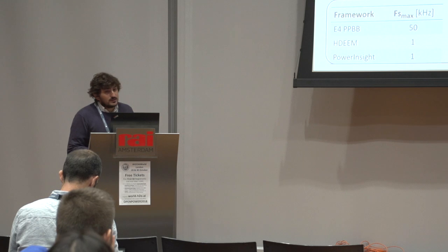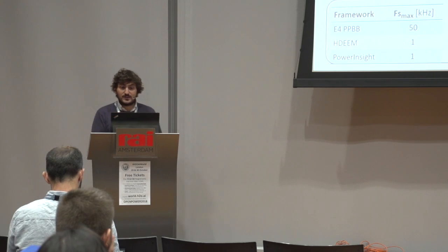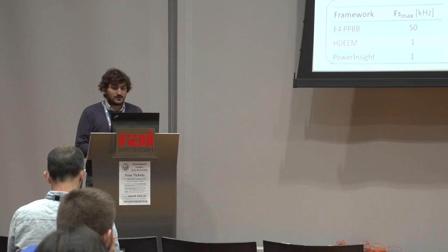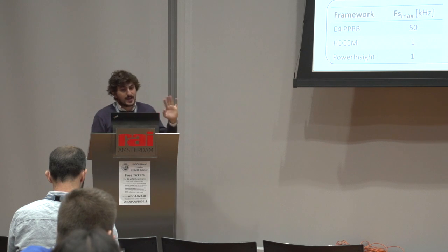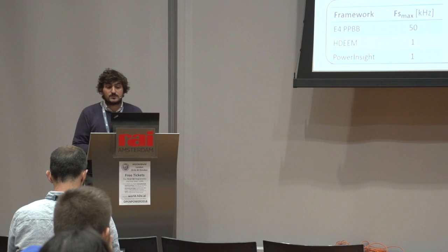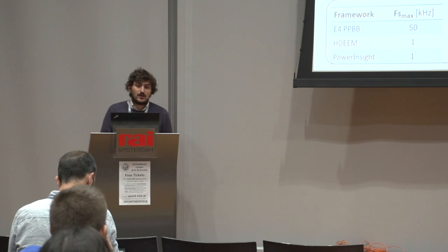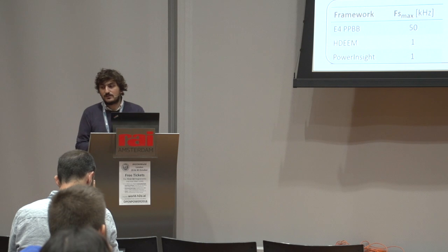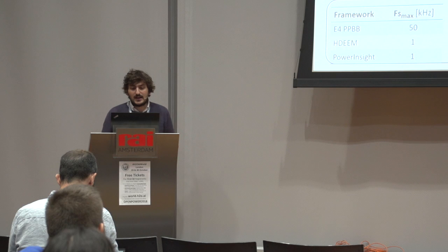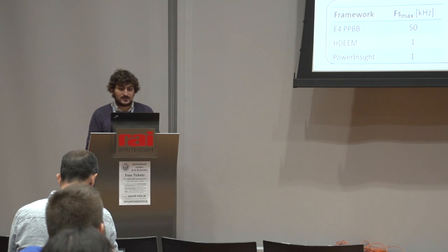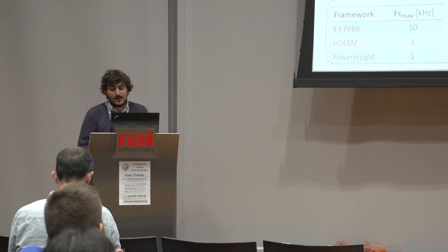The system, looking at the fine-grained performance, is pretty unique. It's capable of sampling the power consumption at 50 kilosamples per second with high accuracy, and with support for time synchronization protocols, NTP and PTP. So we can align the power consumption readings between all the nodes of the cluster. We can have a kind of live oscilloscope for the entire cluster, and it compares favorably with state-of-the-art monitoring systems and competitive products.